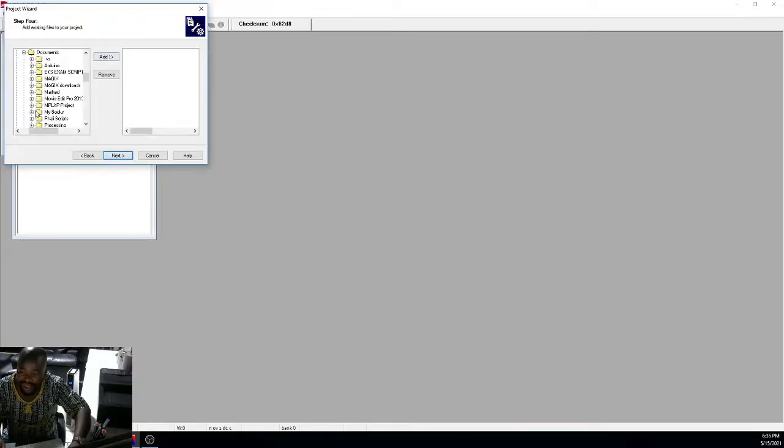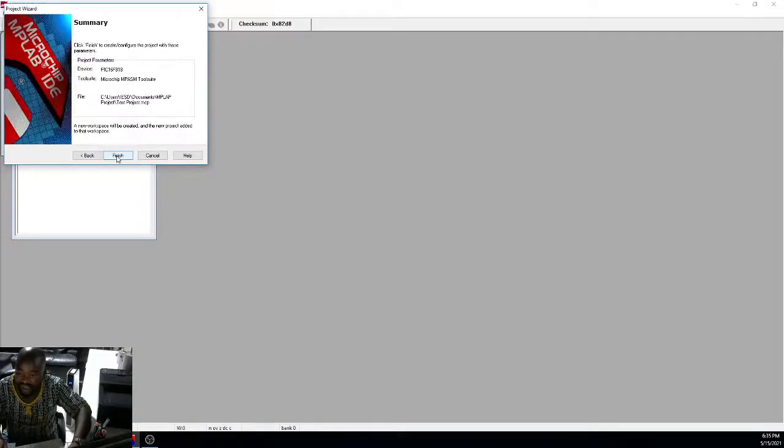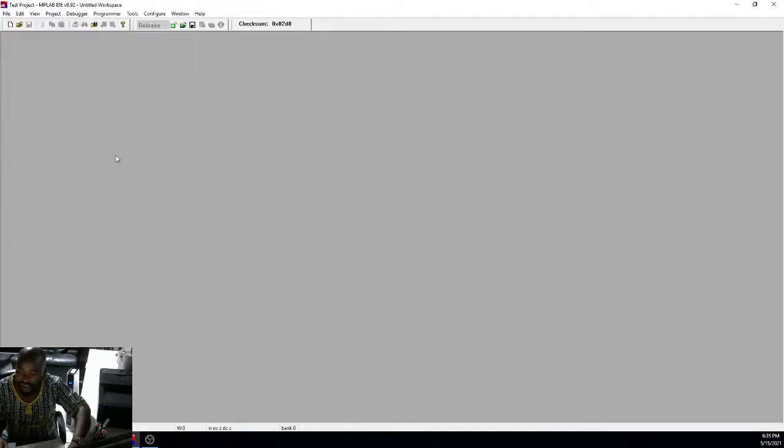There's nothing to add here. For this project, there's nothing to add. We don't want to add files. We don't have any files that we wish to add at this point. So you click next, and then this is just the summary of the project you have created. The device you'll be using is PIC 16F818. The tool suite is Microchip MPASM tool suite, and then that's the location of your project file. And then you click finish.